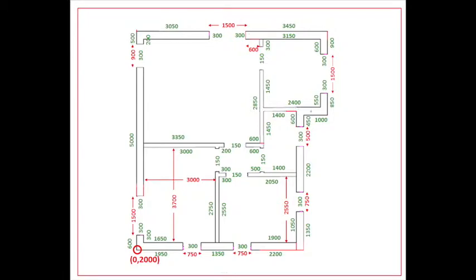Having no lines here means that this whole wall system is one homogeneous wall, meaning it could be a reinforced concrete. It will not be a CHB or a mortar block or a brick, but one homogeneous reinforced concrete wall or retaining wall, whatever, which strengthens my theory that this whole building contraption could have been a floor plan of an earthquake bunker, whatever. So having said that, let's continue.